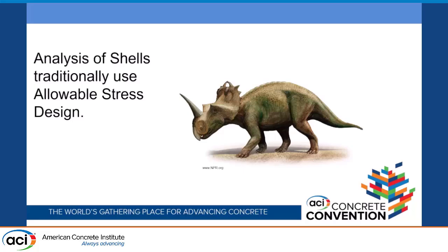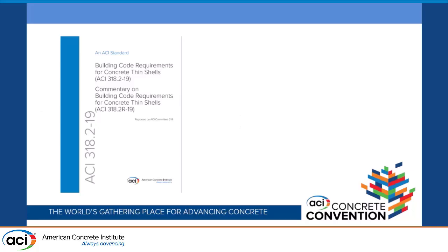I mean, the strength is fine in a lot of things, but we have to design them for stability and other deflections and things. And so we want our stresses to be very low. And so that's why we look at ASD design. That's why it's a good check that our allowable stresses are very low, just like they were during the ASD period. Okay. If you look at shells, there's the shell chapter or the shell book, as it were.